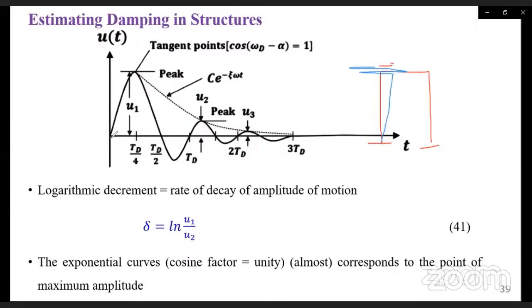So we have now a typical damped motion here. In this typical damped motion, we are showing the initial displacement is equal to 0. In this case, because it's free vibration, the motion was not caused by displacement, it was caused by maybe just a push. And because of that push, there's the initial velocity.